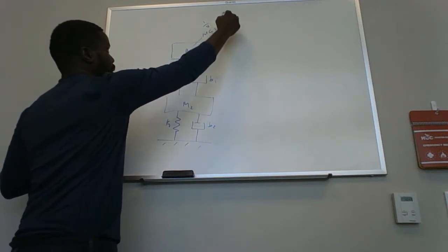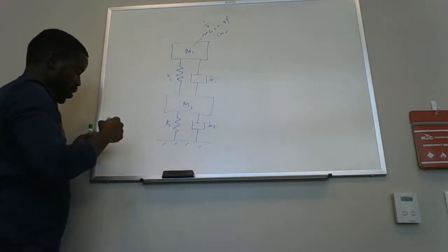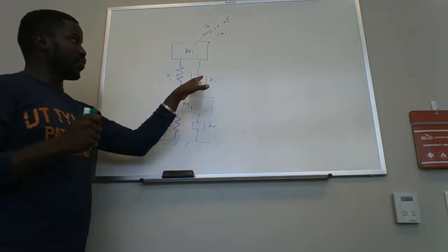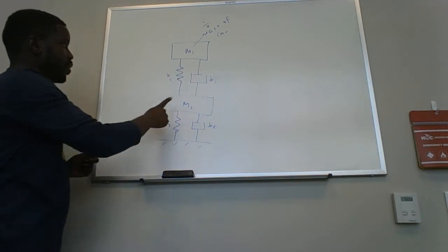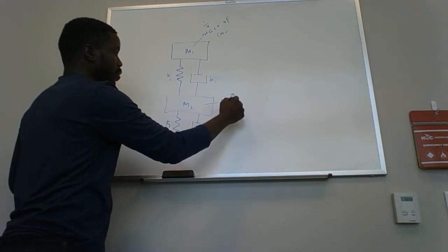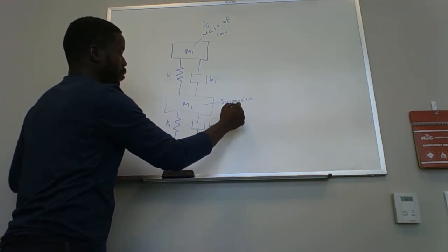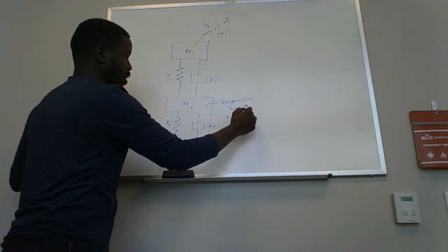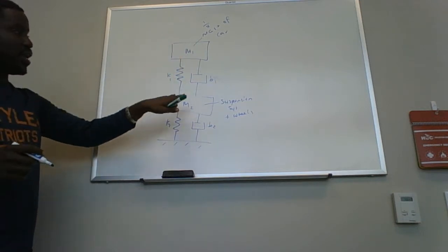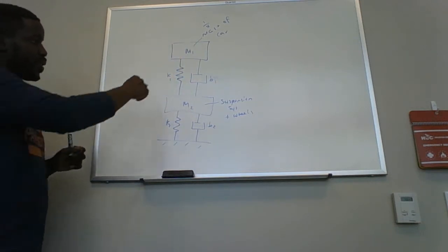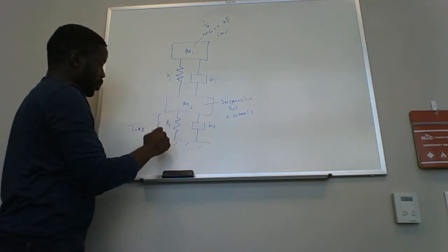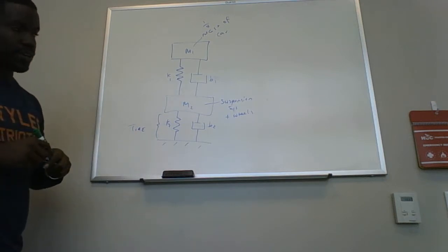1/4 mass of the car. Here you have stiffness due to the suspension system and friction, which here is denoted as a damper. And then here you'll have the mass of the entire suspension system, plus the wheels or anything else that's attached that's being compressed. So this part of the mass is uncompressed, and this part of the mass is compressed by a spring. And here we represent the tire. So this section represents the stiffness of the tire as well as the friction due to the tire.